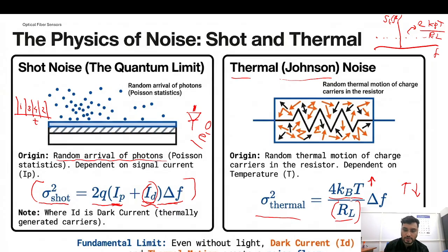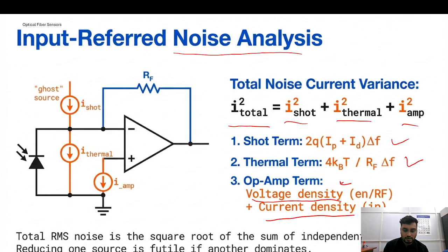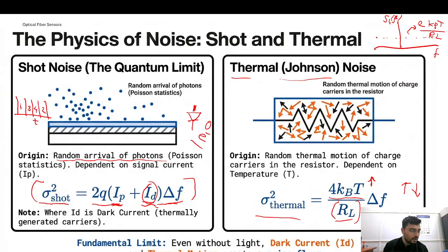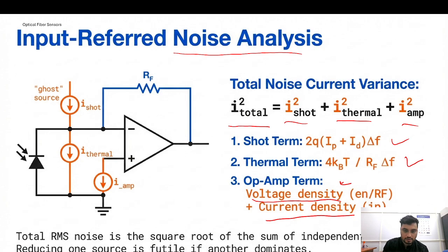Dark current also depends on the temperature. Then shot noise, the random arrival of photons, how will you get rid of it? Averaging out. Apart from that, how will you improve accuracy? Calibration. Precision, the number of times of data collection.